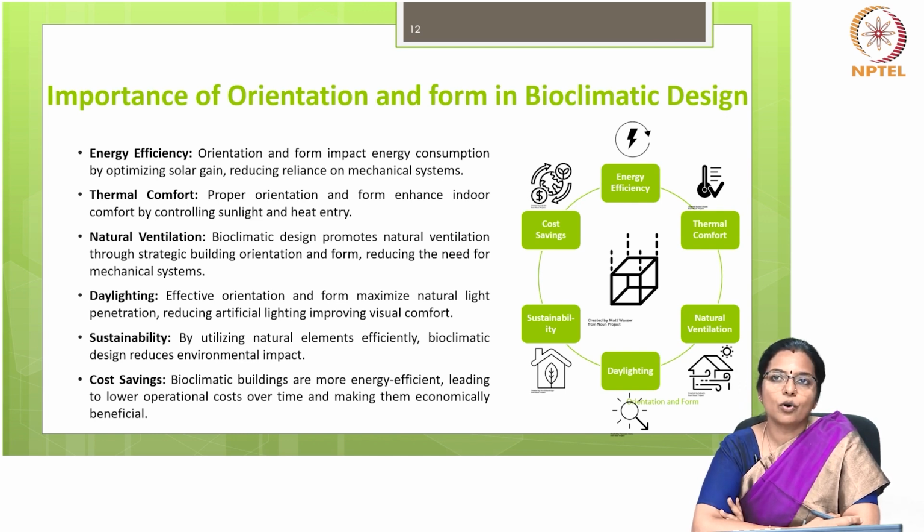So, orientation and form are fundamental pillars of bioclimatic design, crucial for optimizing energy efficiency and enhanced occupant comfort. This is especially true because it doesn't really cost much to understand which orientation is best to place a particular building design. For a given spatial requirement, the building plan form should also be arrived at in such a way that it helps in energy efficiency of the building through bioclimatic design. And these actually do not cost much, because this is actually the process and the work of the designer.